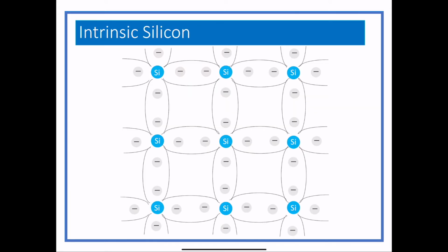So this is what silicon looks like as a structure. You'll notice that each one of these is sharing electrons so that it looks like each atom has 8 around it. In reality, each one is providing 4, and they're just sharing the electrons between them. And if an electron gains enough energy, it just flies off into the conduction band, and it leaves a hole behind. You like that? That was fun to do.